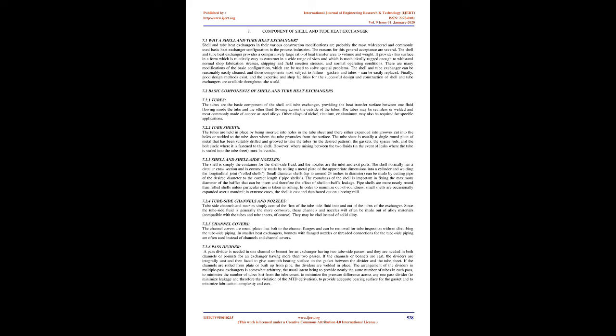In that paper, both the models are derived for a shell and tube heat exchanger with pure maldistribution, without backmixing, in tube side flow and plug flow on the shell side. The Mach number and the boundary condition, which play a key role in the hyperbolic dispersion, have been derived and compared with previous investigation. It is observed that the hyperbolic model is the best suited one as it compares well with the actual calculations. This establishes the hyperbolic model and its boundary conditions.